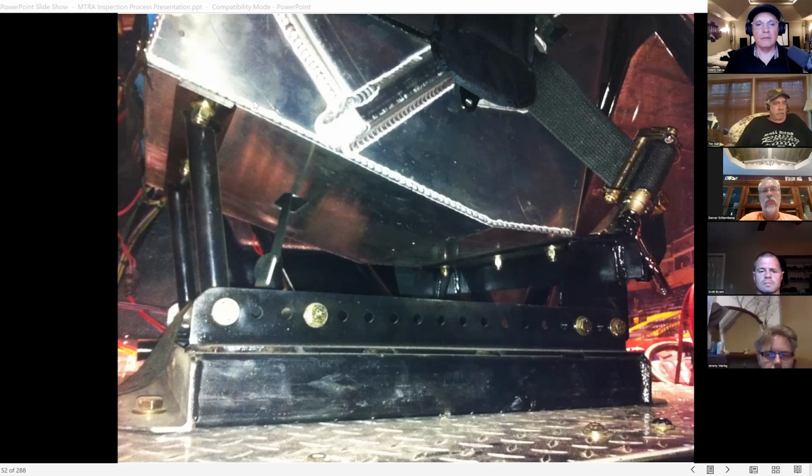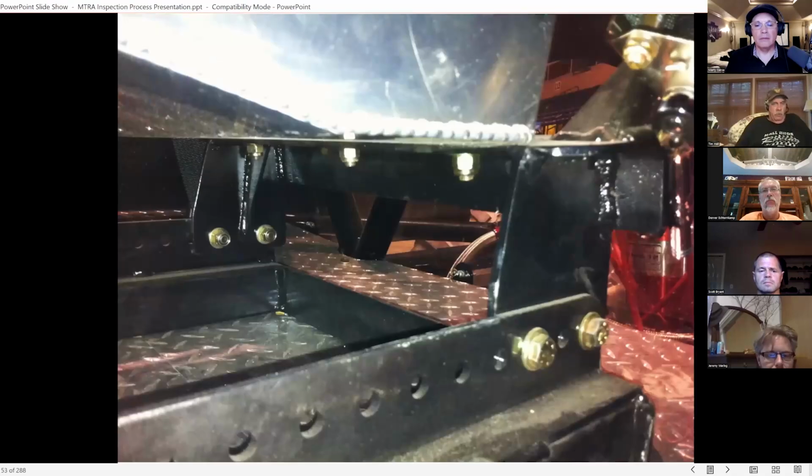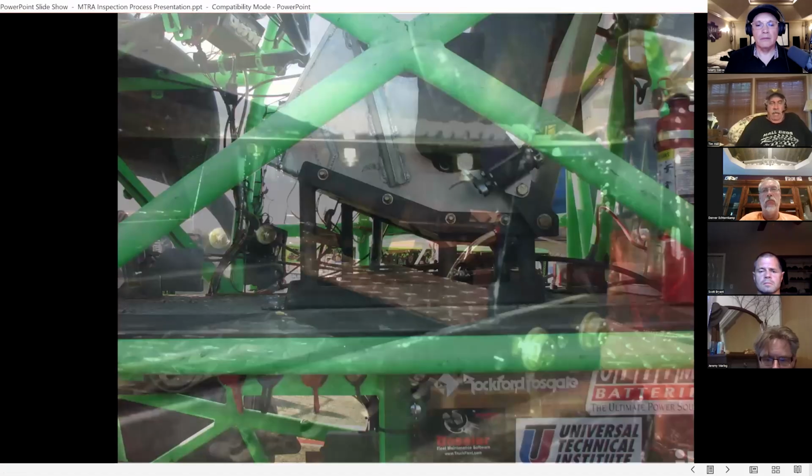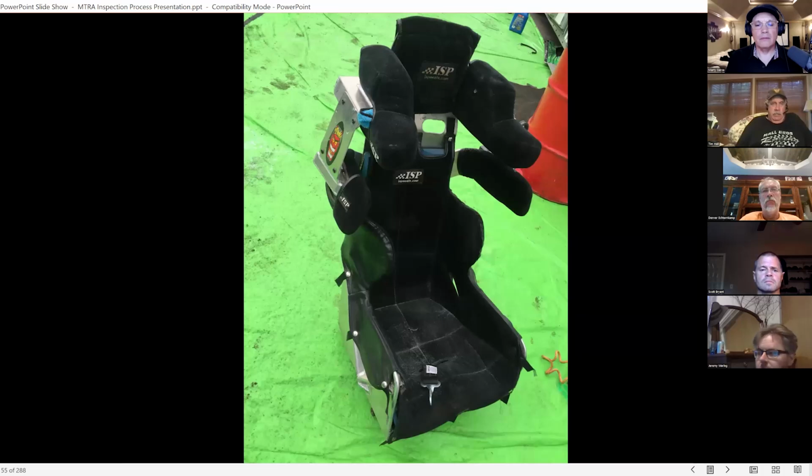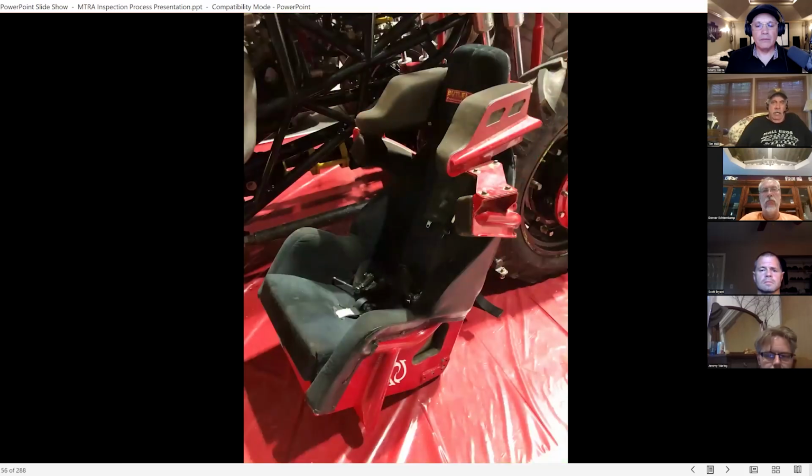And it's got to be bolted in, mounted in correctly to the frame or the outriggers with minimum of 4 3/8-inch grade 8 bolts. So, you know, how it's mounted is important. The greatest seat in the world isn't worth a damn if it's just half-assed in there, and then the guy breaks loose when he crashes, and he's strapped to his seat, but he's still flying around. That's no good. So make sure that that seat is in there in a good workmanlike manner. These seats are big. In order to be in there properly, they're going to need to be attached at the bottom and the top.